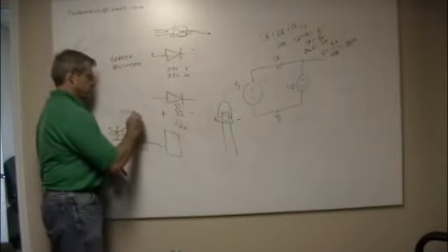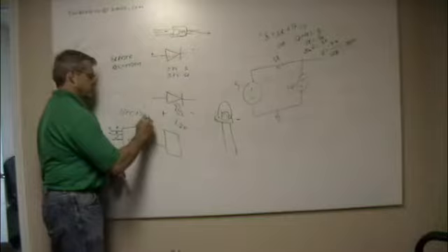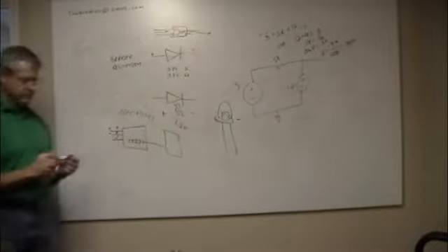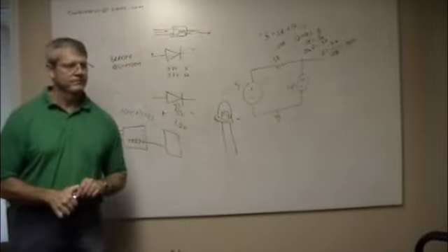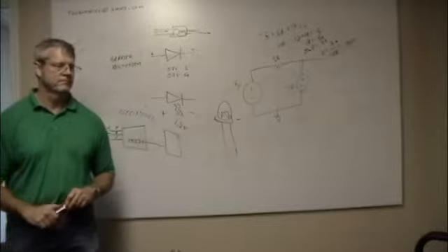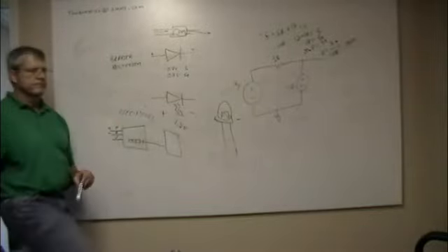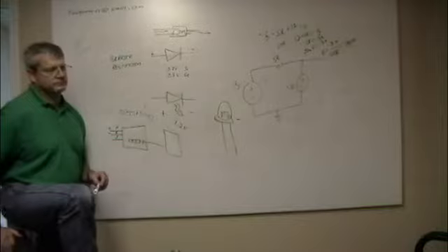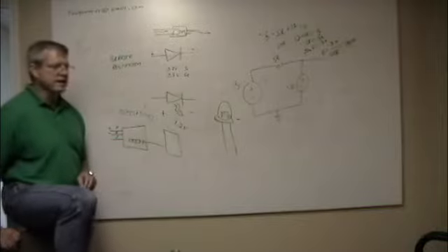Yeah. Neopixel. This wasn't a Neopixel one. Those are the tiny little ones that you can get in the circles or the lines or all the different shapes. This was a more traditional LED, but 8x8 grid, bicolor, and programming wise, you send the data and then you say refresh.